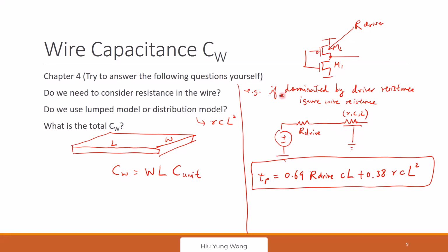Professor, just to clarify, so we're having the distributed delay just because the wire has that much of an impact on the overall delay. We have distributed delay because the wire has resistance and also capacitance, and they cannot be ignored. The wire itself has this delay, which we proved before. Remember? Yeah, I just wanted to clarify. Okay, thank you. Okay, great. Thanks for the clarification. Sometimes I did not hear your question correctly. Forgive me, but it's very great that you ask questions.